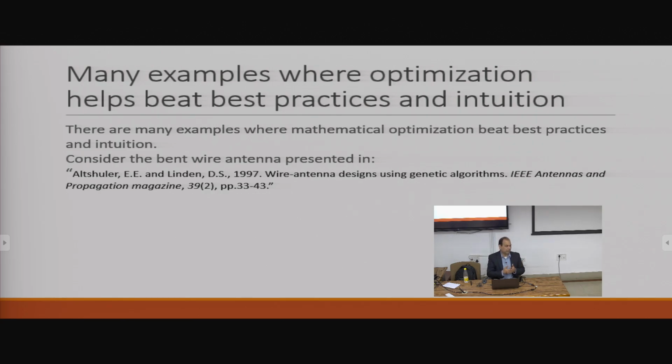So, at this speed and this torque, you change to the second gear, and then you change to the third gear, and so on and so forth. So the model actually was able to implement that. He was able to change the shift points using an optimization algorithm and improve the efficiency by almost 20%, right? Because he used mathematical techniques.